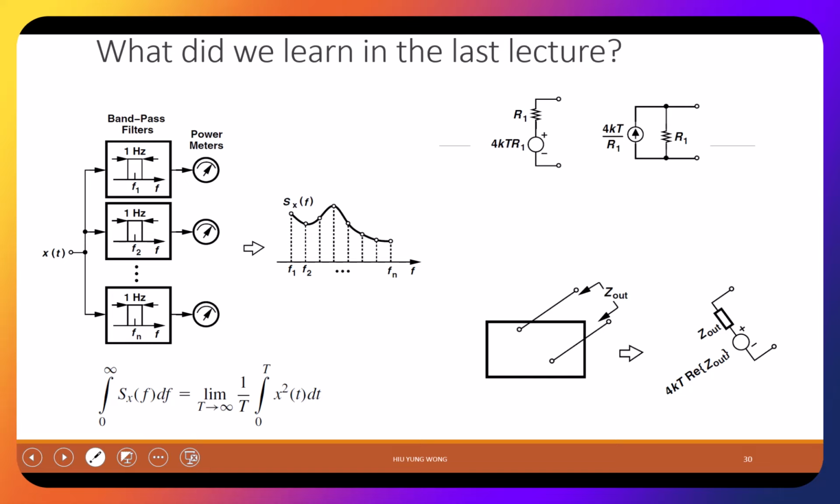We talk about the noise. This is very important. You should know that a resistor can have a 4kTR as a voltage noise, or the Norton equivalent 4kT divided by R if you want to make it a current source, right? But no matter how complicated the circuit is, if you look into the port, the noise generated by this circuit is the real part of this impedance times 4kT, which is easy to memorize. Okay.